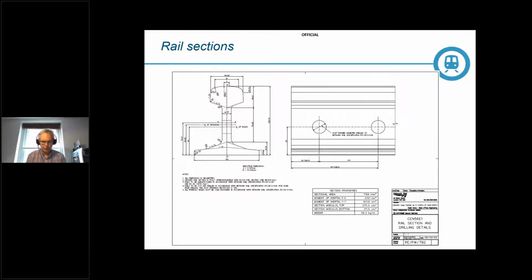These are supported by Euro norm standards giving rolling and material quality tolerances. Network Rail's own standard, TRK 061, called Pearlitic Rails, contains the manufacturing requirements, including testing and chemical composition. Together they form the specification for the supply of pearlitic rail sections. Similar specifications exist for other track components such as cast AMS crossings.